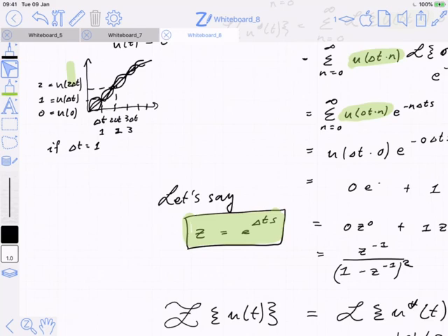The one thing that we can do is recognize that the Z transform on the right-hand side of the table corresponds to a ramp. So I can write down a function of time that will generate the same values at the same points. But that's just a possibility. It's not the inverse, right? It is a function which generates the same values at the same points.